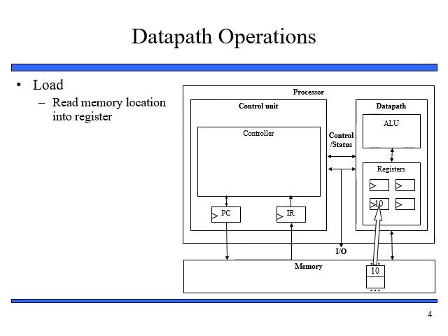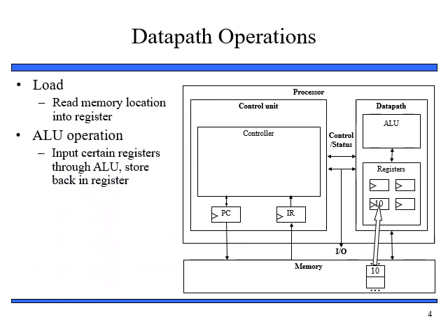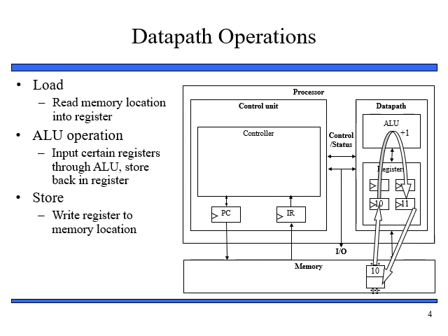So you can see. Now ALU operation, from register the contents goes to ALU. After incrementing it come back to register. Now the content is 11. So the operation that is performed by ALU is to increment 10 so that you can see increment takes place in ALU, and now the value of 11 comes to register, and then in final stage we can write register to memory location. So now write the content of register to memory location, so 11 will be stored in the memory location. So this is how we can perform operations in Datapath.